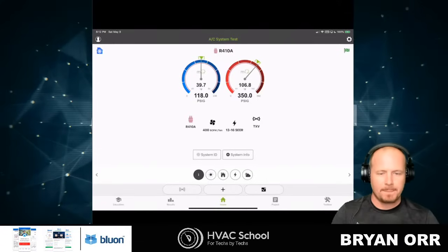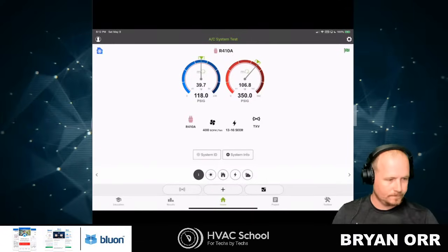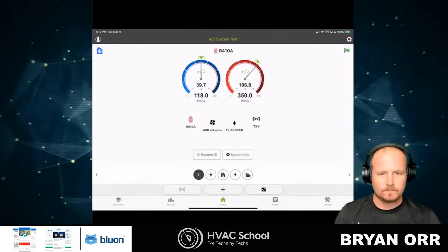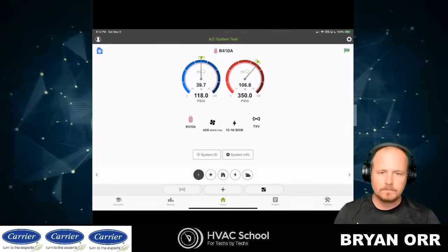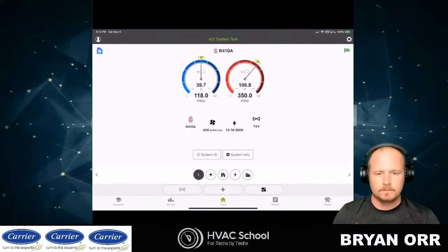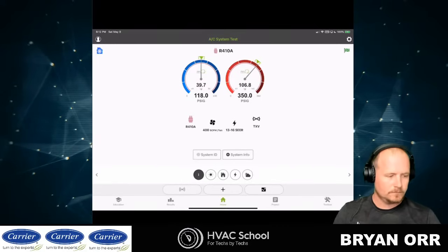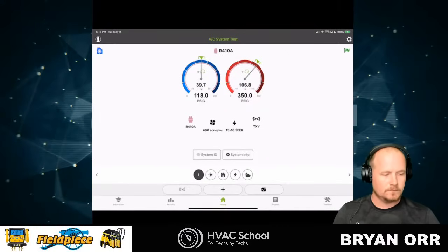Yeah, if we really get into design of equipment, we're realistically specking the airflow, like maybe 375 CFM per ton to get the latent sensible split right, or maybe you've got to add additional refrigerant charge because you've got a lot of length and lift on a line set, or whatever the conditions might be.